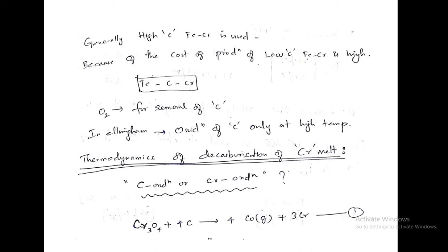So whenever we have carbon, we have to remove the carbon in the stainless steel making process, right? Only chromium by itself gives corrosion resistance. This chromium carbide formation is what they call sensitization, right?